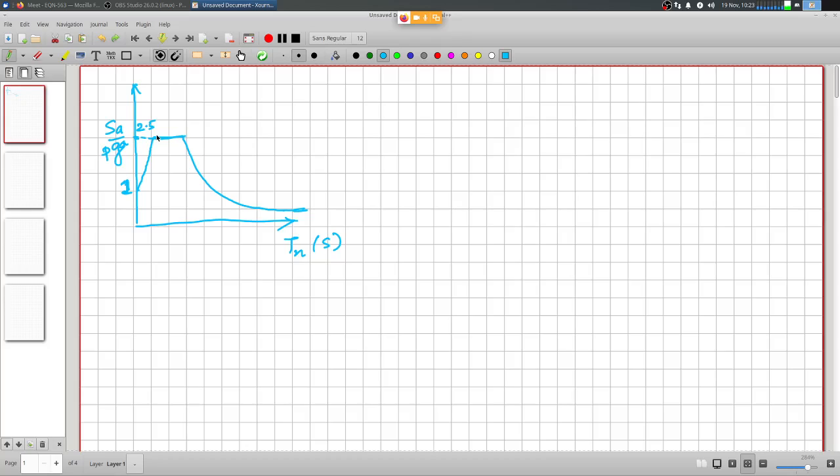That is to take care of the situation when you are dealing with a very stiff system with natural period less than 0.15, that is the period here, right? If you are dealing with a system whose natural period is very small, less than 0.15, it can very well be because of modeling errors. You can model something as a very stiff system, and then it may not actually turn out to be very stiff.